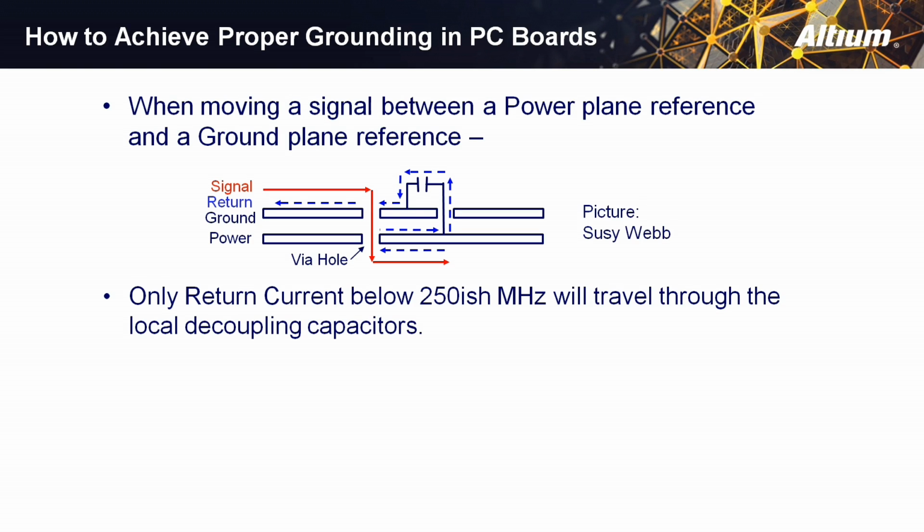What if it is a higher layer count board? What if you have a higher frequency IC as opposed to a microcontroller? What if you had a high-speed microprocessor or FPGA or high-speed memory, all of which, by the way, have nominal operating rise and fall times of about 500 picoseconds, which means that their upper end frequency isn't at clock frequency, it's up close to 1 gigahertz. So most of today's processors have harmonic frequencies that extend to 1 gigahertz or 2. So how are you going to move that energy through that capacitor?